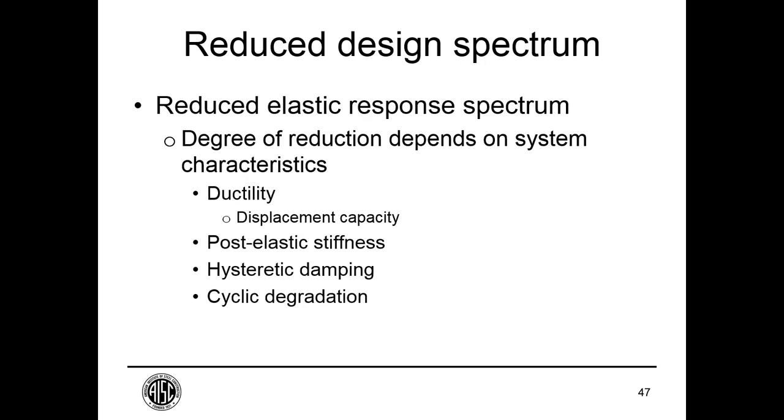The damping that the system has generally shows up in analyses of the system as reduced response. And so systems with a lot of damping tend to have higher R factors. Also, systems that degrade tend to have increased response and generally have lower R factors.